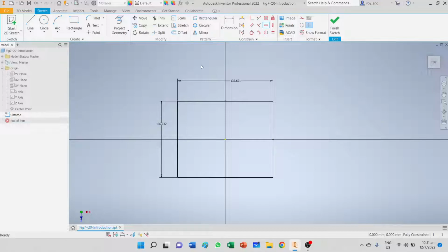So that's a lot neater, and it's one of the preferred ways. This is a preferred way, so that your planes are exactly at the center of your rectangle, and that makes it easier to offset and do future operations. So make use of this. As I progress along the other examples, I will show you more constraint commands. But for now, let's deal with a simple square. All right, and we can change the dimension of a square.